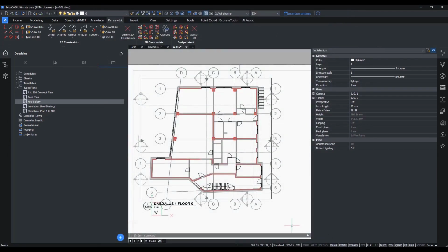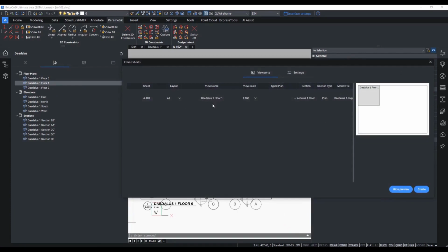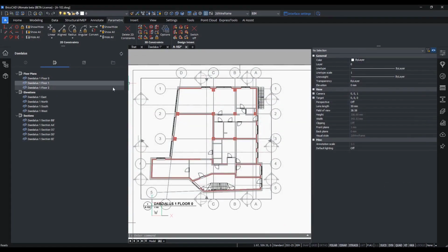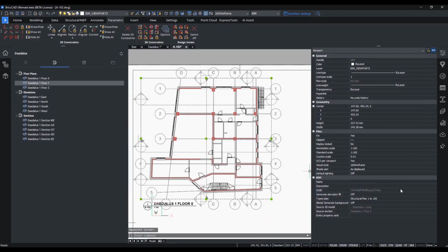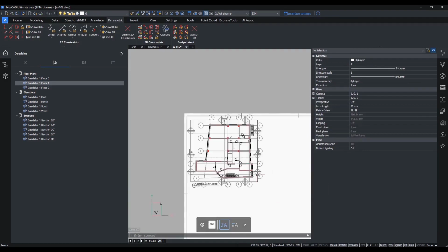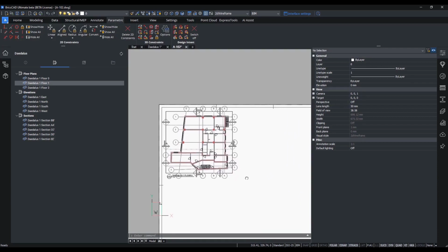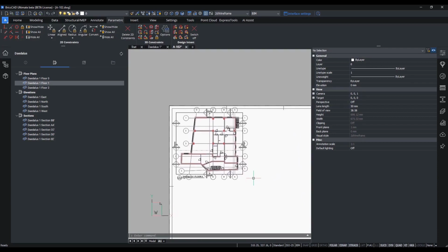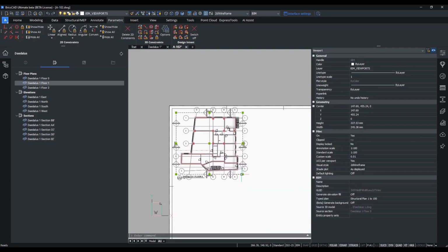And that's it. As soon as we imported these type plans, we can use them in the Create Sheets dialog once again. Or find the imported type plans in the Type Plan drop-down property list of the viewport. Now, if you want to generate multiple times the same section entity, but with different type plans applied, that is no problem either.